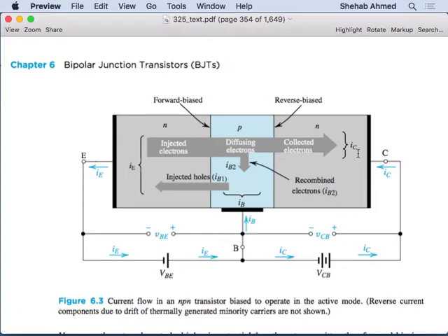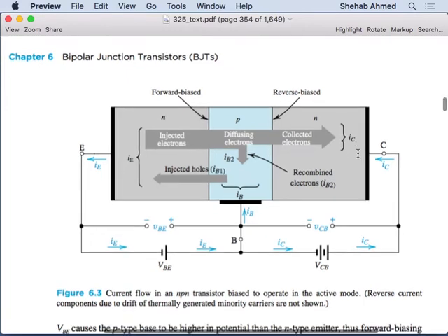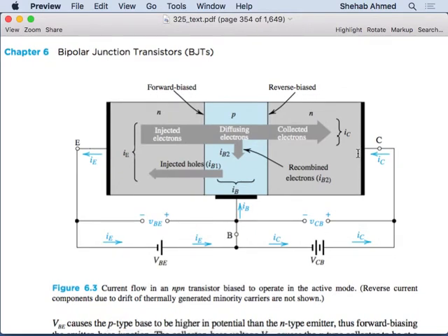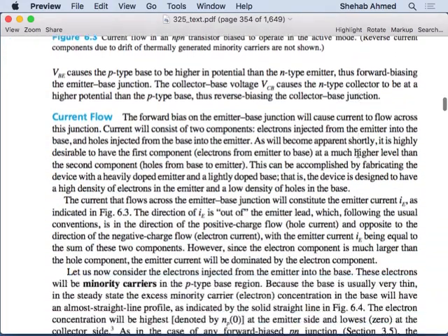And they will all be based on the equation for the diode, which was what? A saturation current, some value, e to the voltage across that diode, divided by Vt, right? We will utilize this equation a lot. And the equation where the difference in voltage versus the two operating conditions for current that we used a lot in the diodes, we will see a lot here as well, right? So this is basically an application of the diodes material.